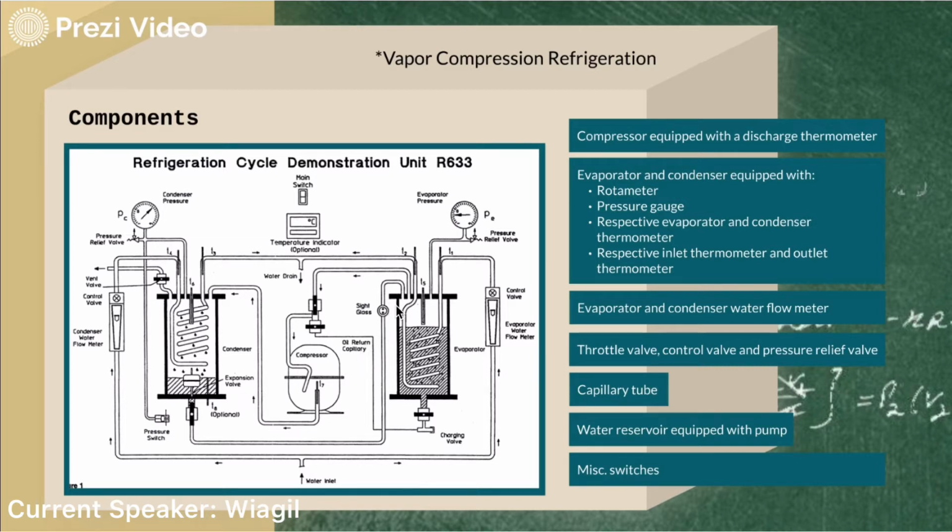Firstly, the compressor will draw vapor refrigerant from the evaporator and begin to pressurize this vapor refrigerant. When this occurs, the pressure is increased, and the temperature of the pressurized vapor refrigerant will also increase. After, this high-pressure and high-temperature refrigerant will leave the compressor and then enter the water-cooled condenser. By water-cooled condenser, we are talking about the coil carrying water, which absorbs the latent heat from the hot high-pressure vapor refrigerant, condensing it into the liquid state.